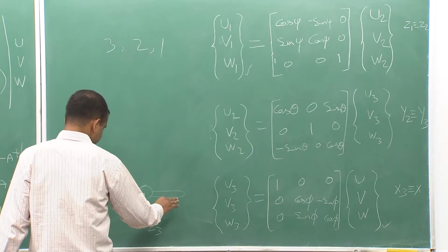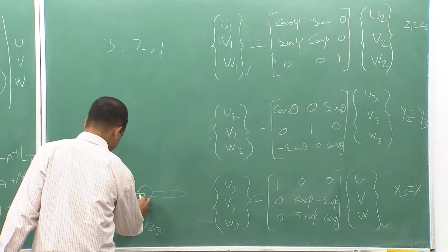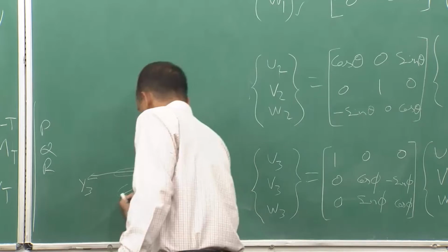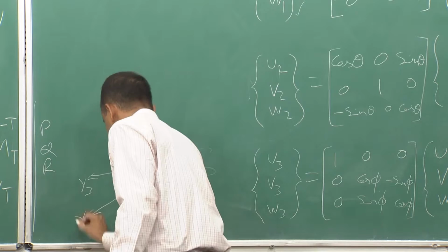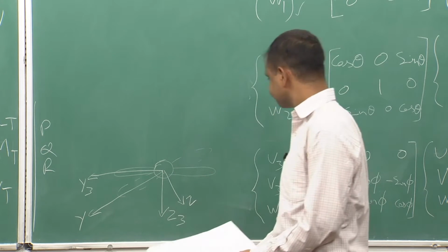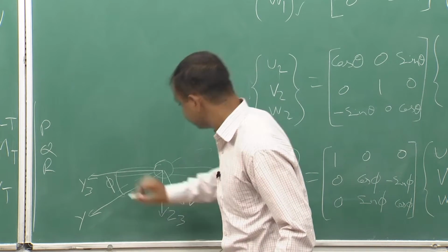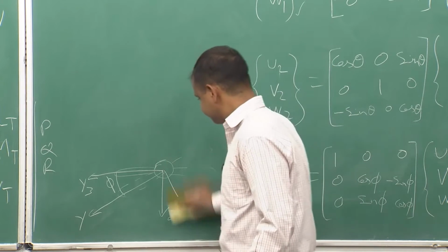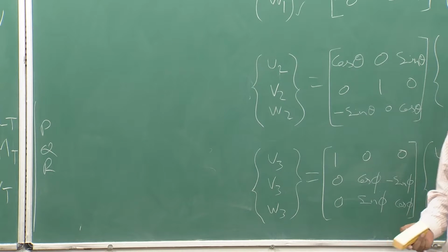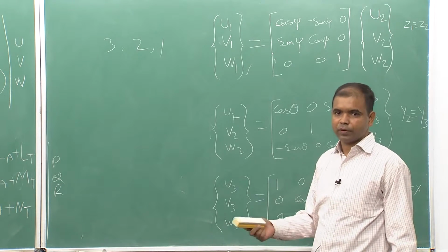So, right wing down means this is my front view, it will become like this, and this is my final y and this is z, and this angle is phi. So, using these 3 rotations we can convert our frame from inertial frame to the body frame or body frame to inertial frame.